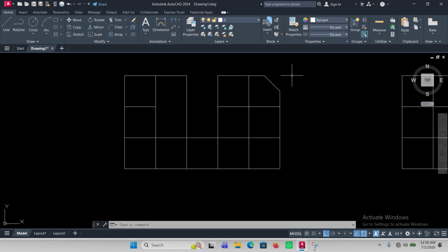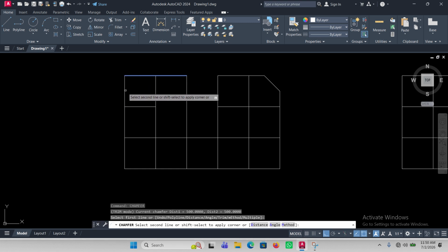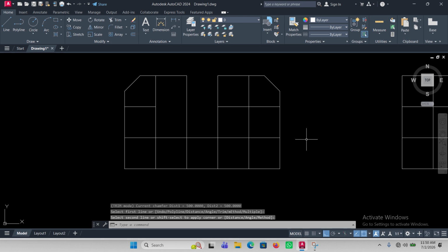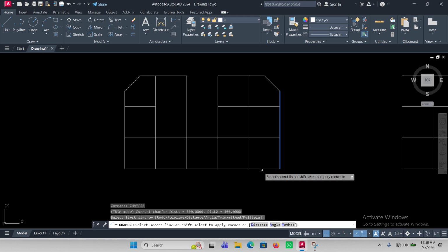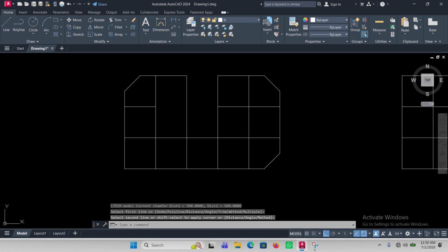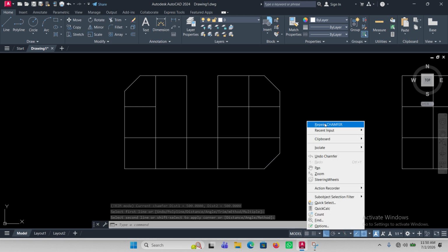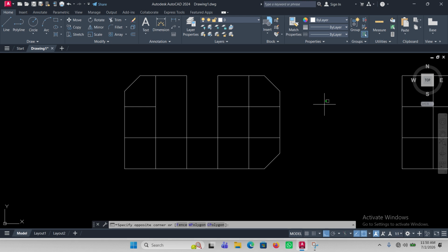I can right click and then repeat chamfer, click here, and same thing. So I right click again, repeat chamfer, click here, and I click here to achieve the same thing. Okay, that is it. We have done our chamfering successfully.